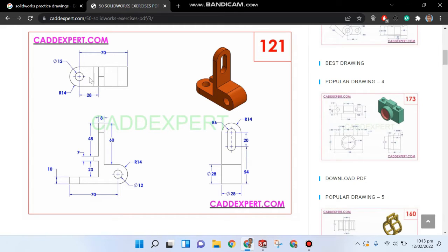The top view you can't select because it will create this whole geometry, and the right view, if you make this sketch and extrude it all the way, is also very lengthy. So this sketch is very good to start, because if you make this sketch and extrude it, there are fewer features left. Okay, let's make this sketch.